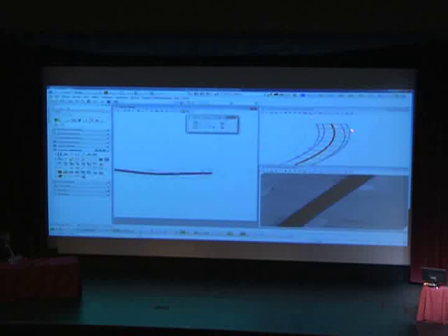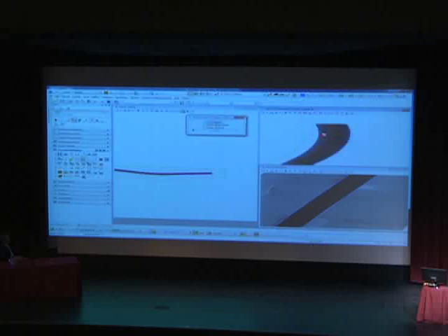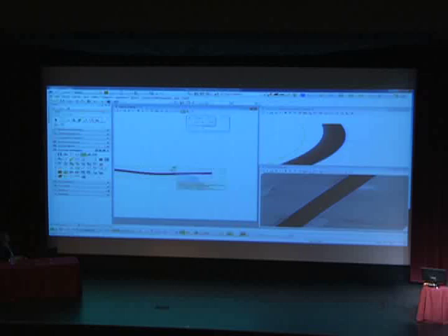And you notice in the top right-hand corner here, the pavement's not connecting correctly because it's at a 30-foot offset. What I'm going to do is use a parametric constraint from station 0 to 9 to transition it from an 18-foot to a 30-foot. And that parametric constraint is going to change everything and make it look a lot nicer. Another thing we're going to be using parametric constraints for is, let's say pavement design changes at 90%. That doesn't happen, right? But let's say it does. You could put a parametric constraint on your pavement to change it from 17 to 24 foot.